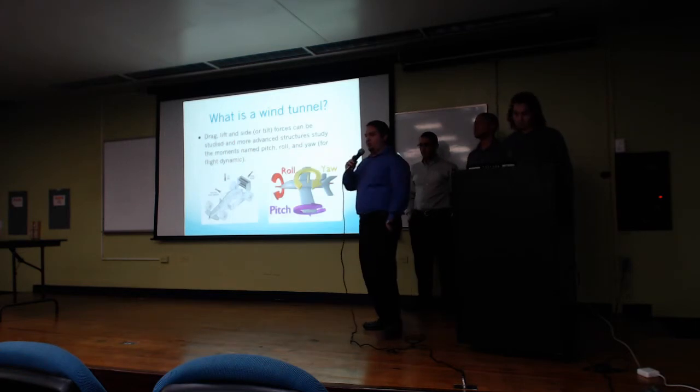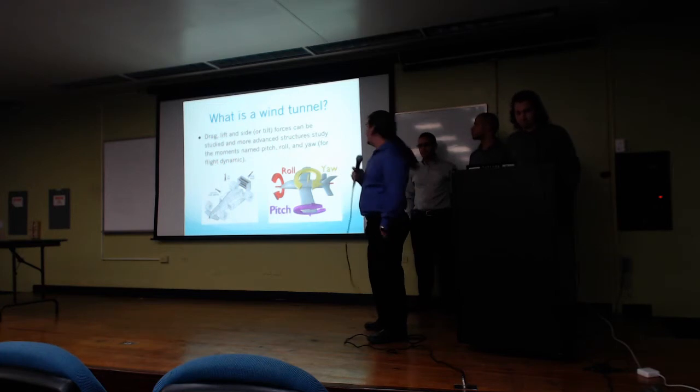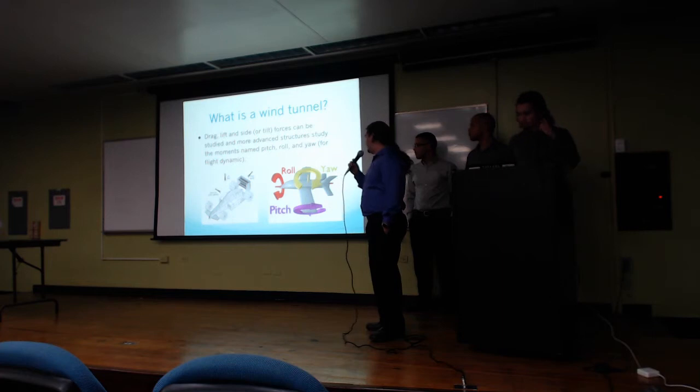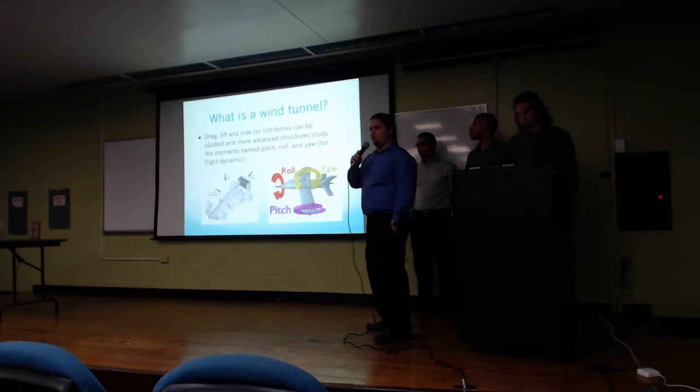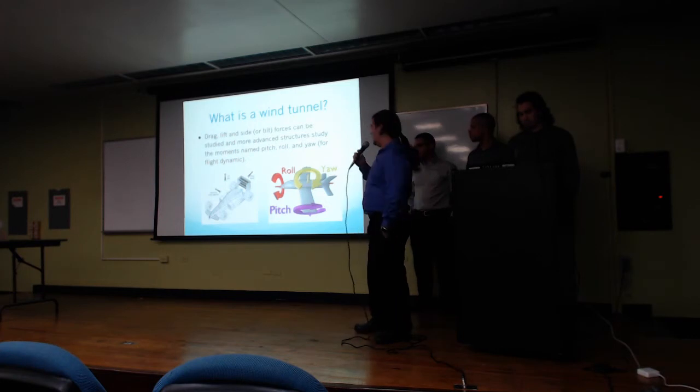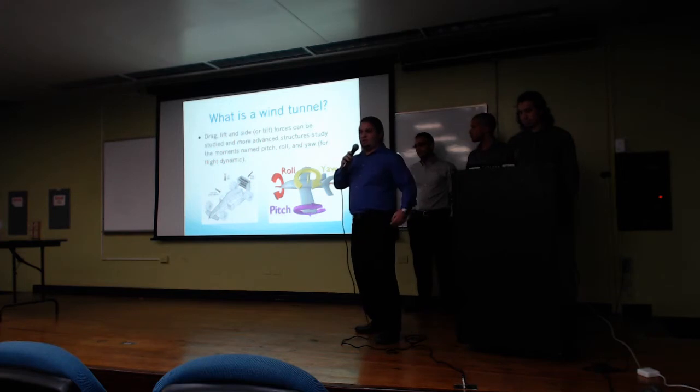We use the wind tunnel to measure forces called drag, lift, and side forces. And it can also measure moment forces called roll, yaw, and pitch. We only focused on drag, lift, and side forces, which you can see on the small car here. Drag pushes the car back, lift pushes the car up or down, and side forces basically make it veer left and right.